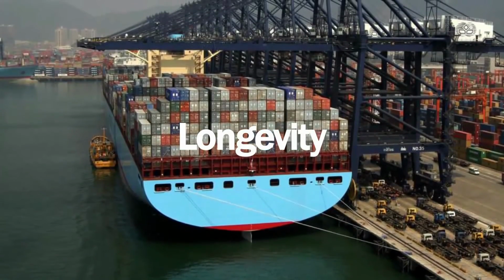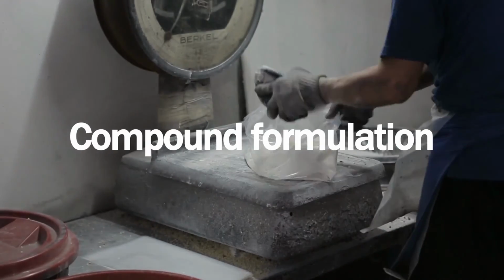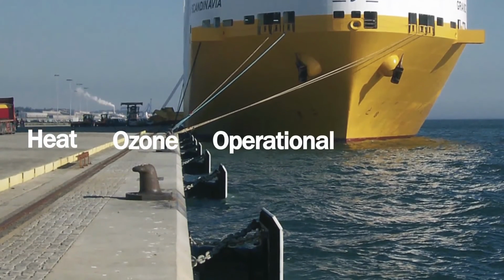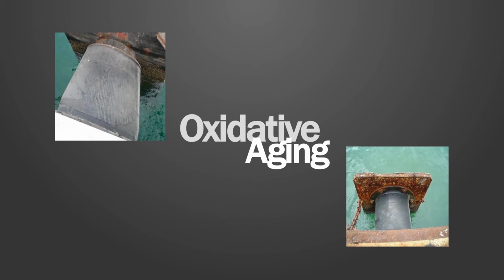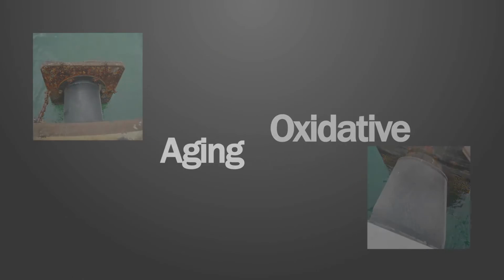The durability and life cycle of rubber fenders depends on many factors: the type of rubber used, compound formulation, environmental conditions, heat, ozone, operational use, and mechanical damage. Oxidative aging, a process described as the change in rubber properties over time, is one of the main issues impairing the functionality of rubber fenders over their life cycle. The mechanisms that produce oxidative aging depend not only on the degradation agent, oxygen, present in the environment, but also the type of rubber used and any additives used in the compound formulation.